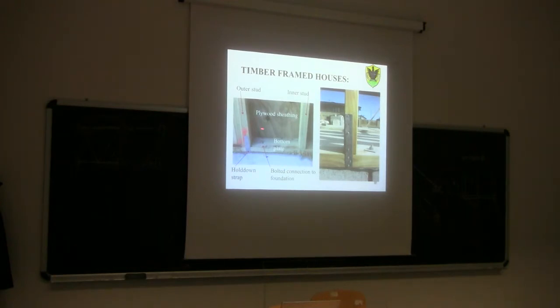And then you see the plywood shifting on one side. This would be the hold down strap here at the end. So this one should actually connect the stud to the foundation. In reality, this is not true. I mean, in this photo, you see this metal plate is not a real strap, it's not a real hold down. This one is a kind of connection done in this way.